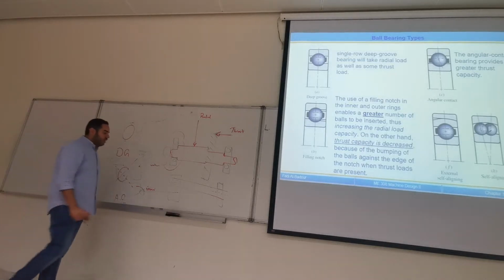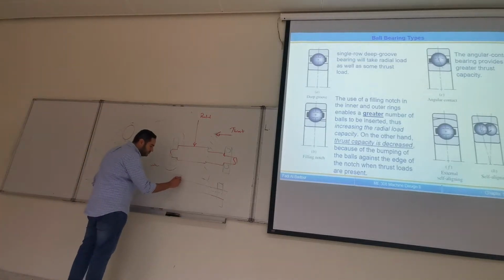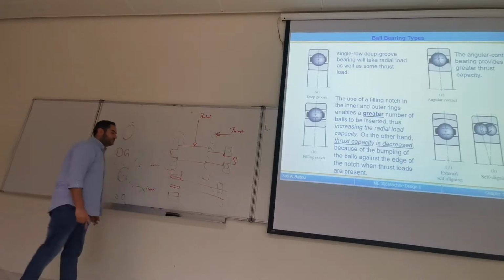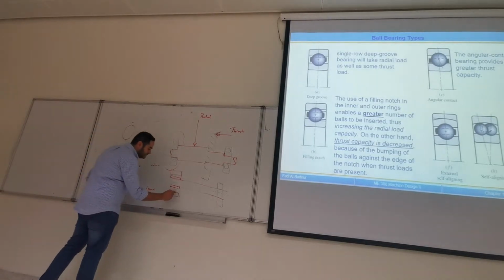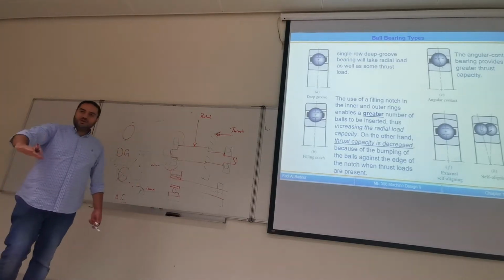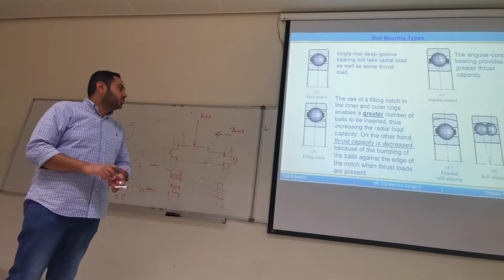Okay? So now here, if I have this is the inner ring. See, the inner ring will tilt with the shaft. The inner ring will tilt with the shaft. But the outer ring is straight horizontally with the housing. So what happens to the rolling element inside? It'll get damaged. So the life again becomes smaller and so on.